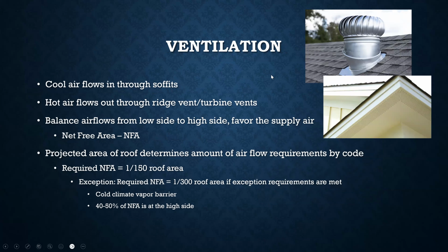Ventilation. Ventilation is extremely important for a lot of reasons, but a very important one is that if your roof gets too hot from the sun hitting it, it's going to break down all the shingles. It's going to kind of burn them up. They're going to get overheated and start to fail, and it's going to wear your roof out much faster. We don't want that.